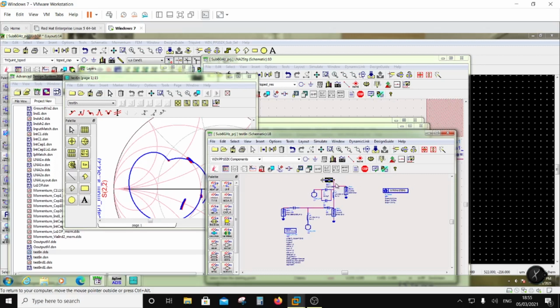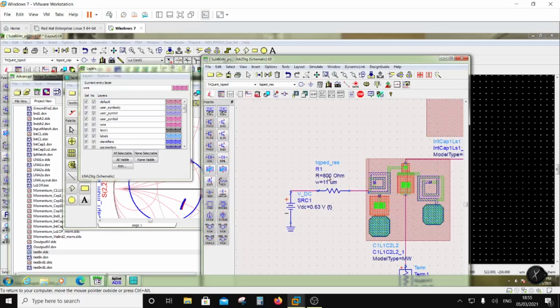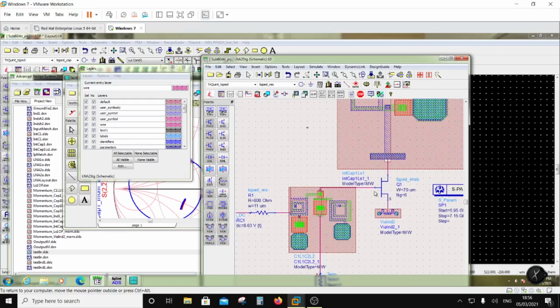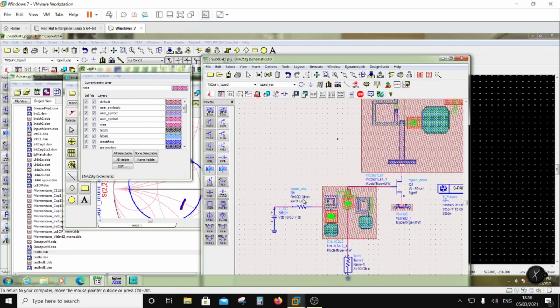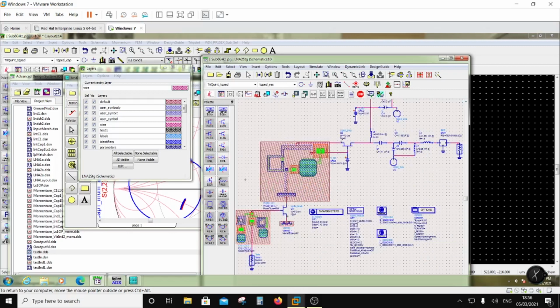So let's just put here an 800 ohm or 1k ohm resistor and see what happens to the noise figure. The issue here was that the noise figure degraded because the match was not correct due to this impedance. So I inserted an 800 ohm resistor, near to 1 kilo ohm, and then did the simulation.